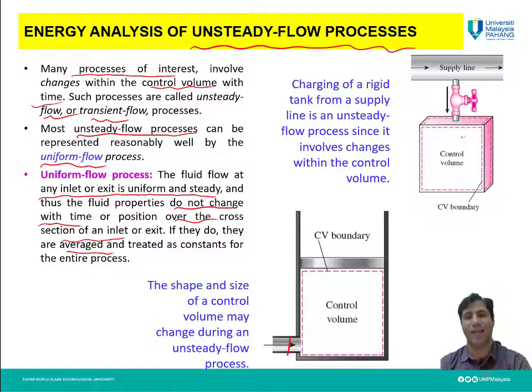Then, as you notice here, if we select the tank as our control volume, or we select the gas inside the tank as our control volume, the flow rate coming to the control volume is changing with time, and charging it is an unsteady flow process since it involves changes within the control volume. The other example is what you can see here.